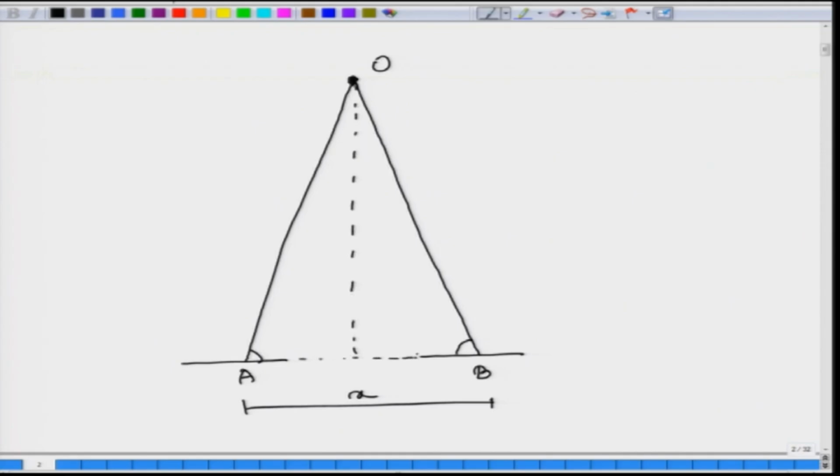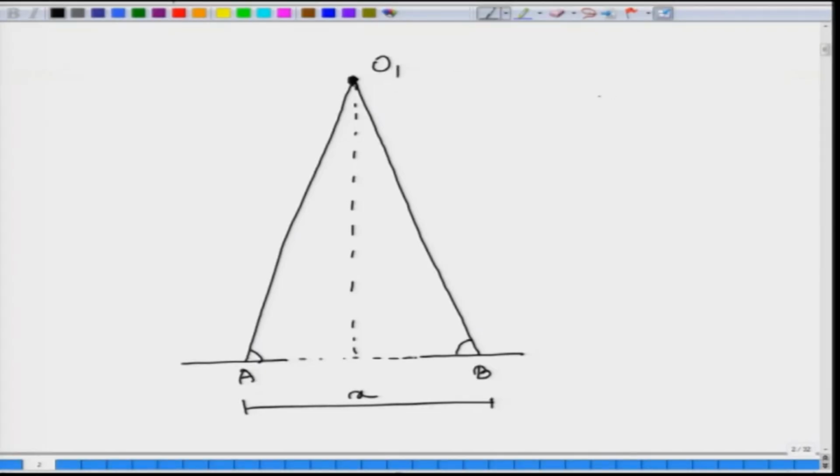So, this is the method of triangulation, and in the case of photogrammetry what we are doing is that we take multiple photographs and we process those photographs in such a way that we are making use of the principles of triangulation to figure out the depth or the distance of different objects from the surface of these photographs. So, if we do that, we will get that say point O1. So, point O1 is located at a distance of D1, and you are also getting the x1 and y1, that is the coordinates of this point on this surface.